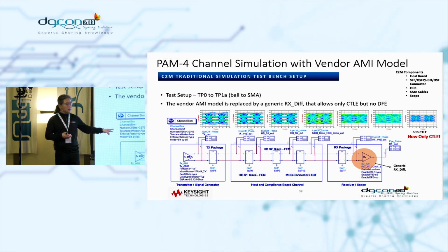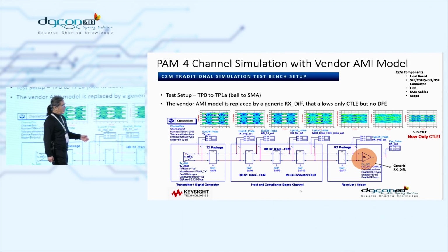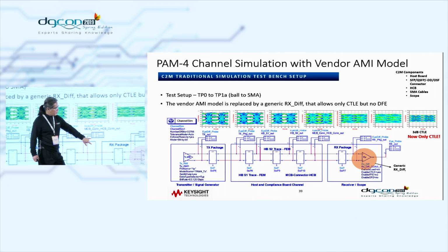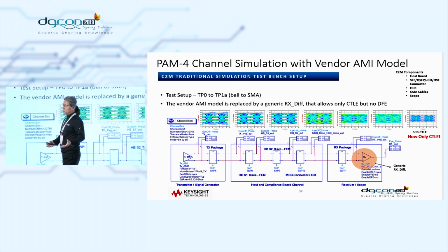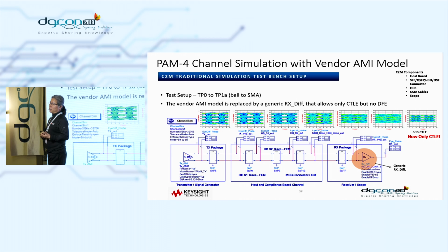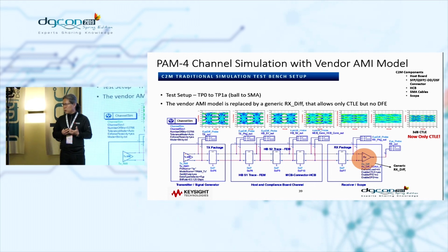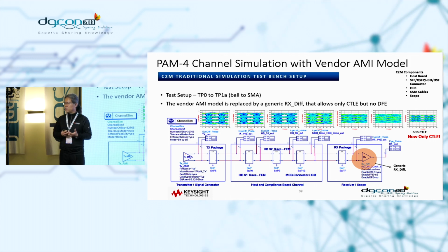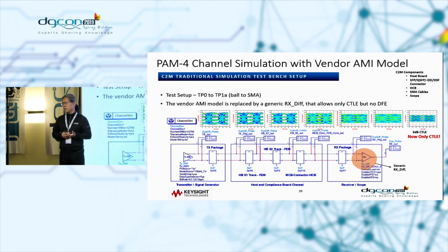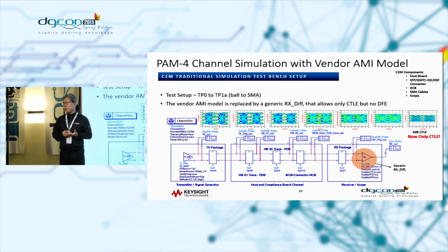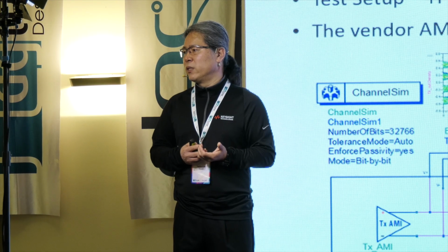In this case, the way we did it is to send the data right after this channel and process everything in measurement software, where I can apply proper equalization and a low-pass filter that represent the scope characteristics. But still, there might be some uncertainty. I believe that is quite difficult to avoid. That's something we have to live with.